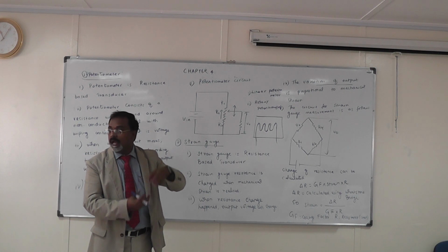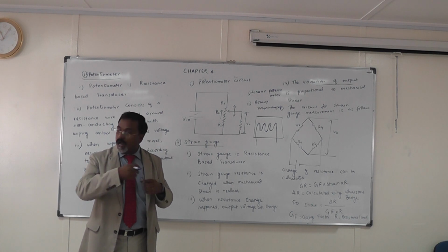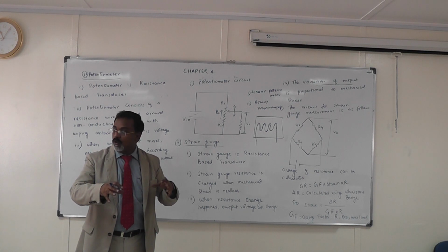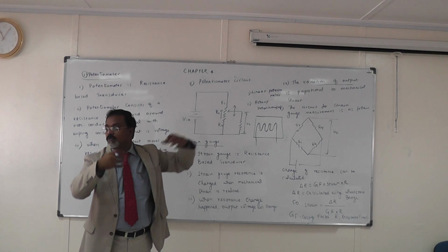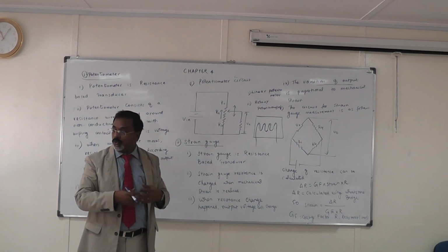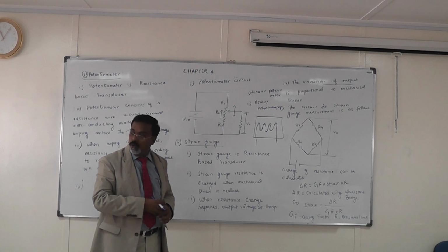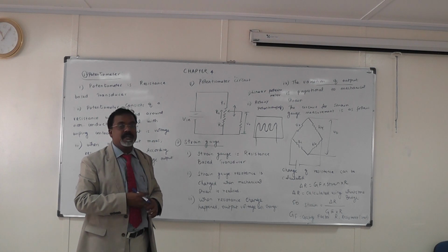Some mechanical linkages will be there that restrict it, and then a small amount of the load will be applied on the strain gauge, and then the strain gauge will give some output. Then a small output change means you are telling 1000 ton or 2 ton or 5 ton or 500 ton, all those things you can measure by using a load cell. Okay, in the load cell we are using these small strain gauges as the transducer.